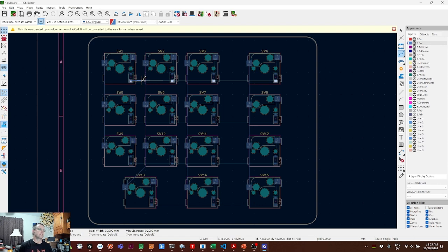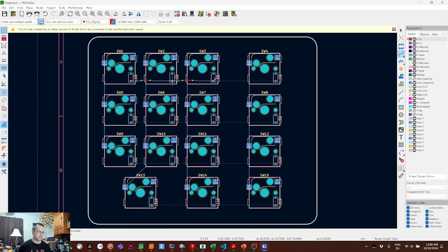It's actually 2 layers. Right now we're drawing traces on the back layer of the board, where the diodes are going to sit. But if we hit the V key and click, we flip over into the shadow realm. Actually, it's the front side of the board. That's what the red color means. You can look over at the layer list here to see that the front copper layer is in red. And our red trace can happily cross our blue trace. We do need to get back to the blue world to get to our diode, so we'll hit V and click again, and then we can get to our pad. Click to start another trace, V click to go over, V click to come back, and we'll connect our diode.